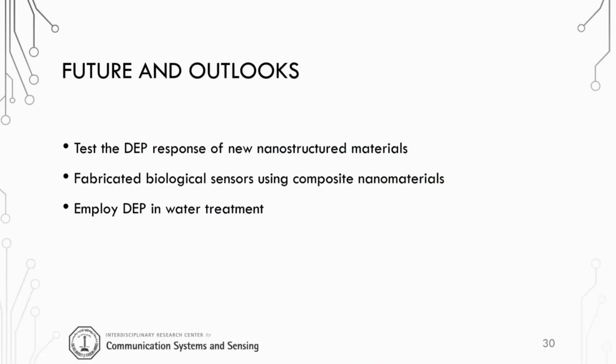Oh, you mean for the testing or for the real application? For testing, we prepare our samples in the lab at different concentrations. For example, we prepare our bacteria sample and then add the medium in different amounts, so that the concentration of the bacteria within the medium will be different. This is also very important for experiments and simulation at different concentrations. If the bacteria concentration is small, of course, the reading at the sensing electrode will be very small. But if the concentration is high, the capacitance will increase based on the concentration. How we control this, we do it in the lab, just for research purposes.